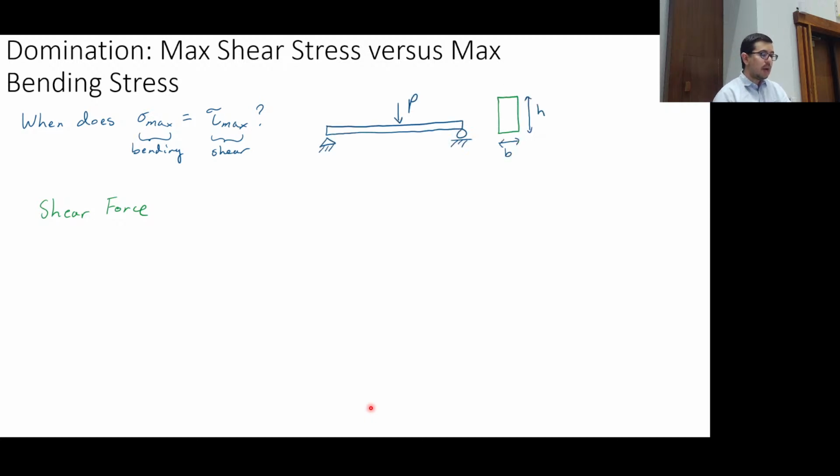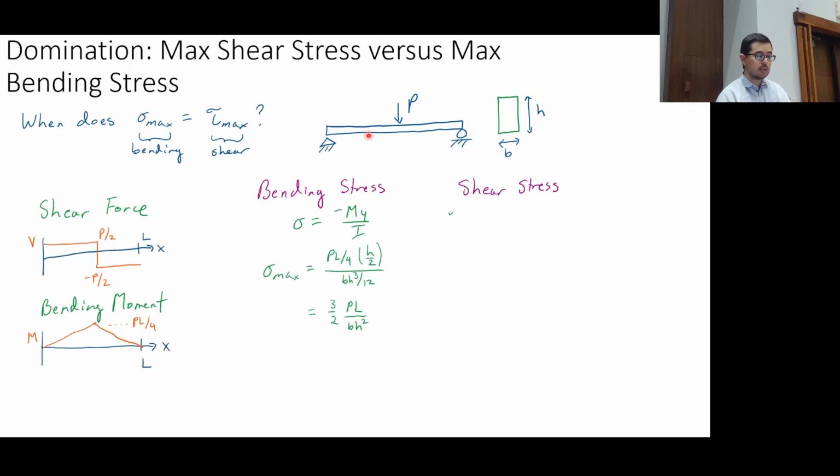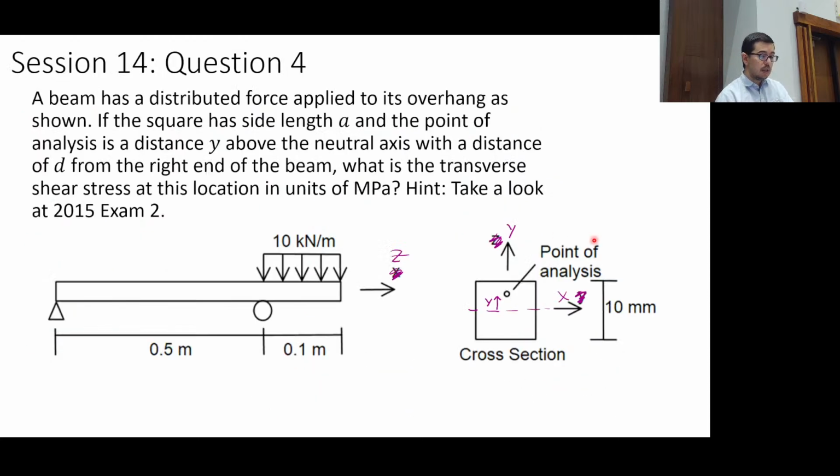We've talked a little bit about when max shear stress and max bending stress, which one dominates, and so we've already kind of done these equations, and now you can look at them from the perspective of saying the shear stress is maximum at the middle, and we can calculate what it is based on, for example, if it's a rectangular cross section, 3/2 tau average. And there will be a problem like this, which I'll do. This is very similar to the last one, okay?